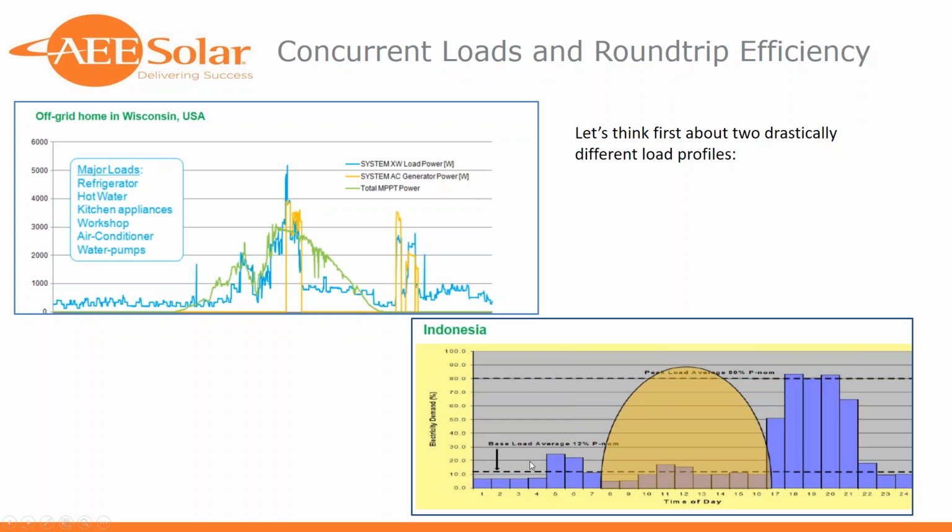Down here at the bottom right, a much different case. The purple blocks will be the load profile through the day, and this has been unitized to percent of total system size. But the loads are very low in the morning through the production cycle here in orange. The loads really don't start until the lights go down. I don't know exactly what type of system this is, but this could be lighting load. It could be cooking appliances. Could be a lot of things. But in my opinion, a better use for this would be a DC coupled system where in the conversion cycle to storage, we're more efficient, maybe a little less efficient in inverting from PV. So two different system sizes.